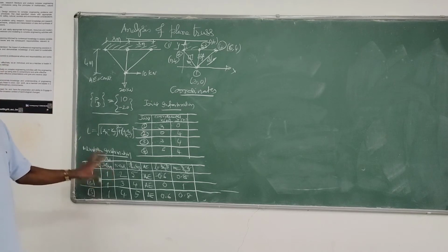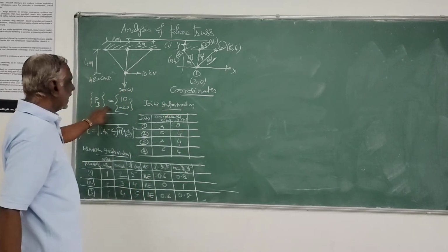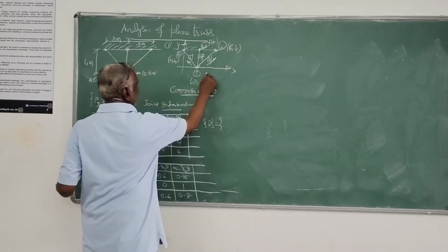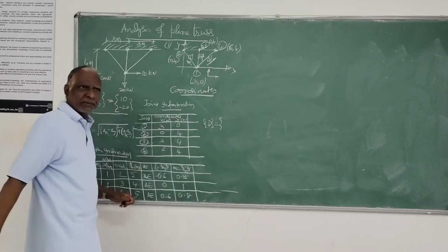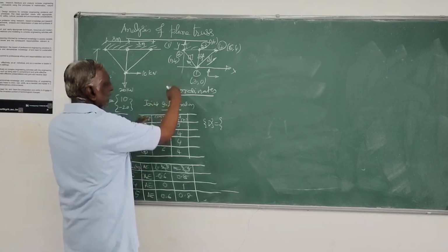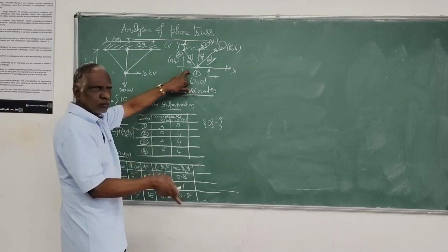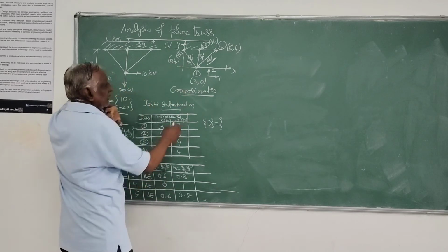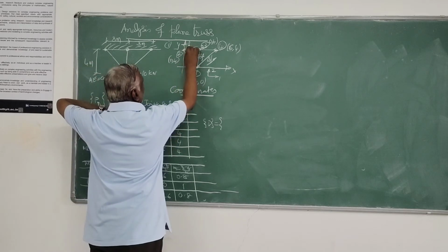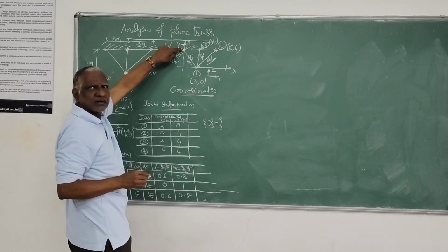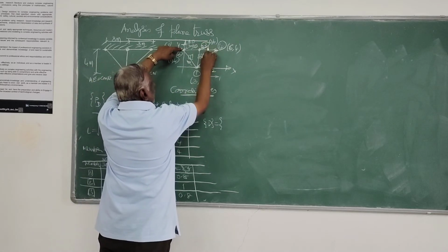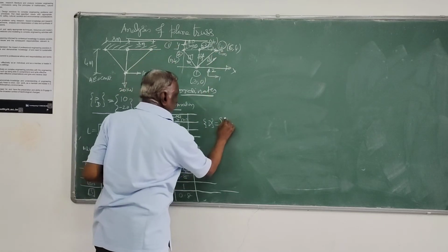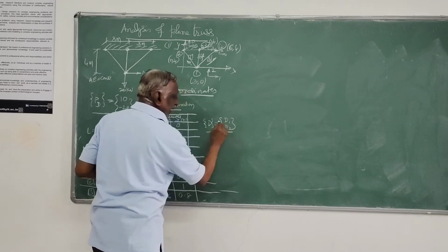That's all the information we need. So now this is the first, PD I have generated, then the PD matrix, then D which we have to determine, or the degrees of freedom I can also write, that is kinematic indeterminacy, as you have done in earlier problems. So here at any joint you can have only 2 types of displacement, no moment. So this is 1 and 2, you can always start with the joint where all displacements are possible, so that you can number first 1 and 2. Here no displacement is possible because it is a fixed support. Here it is 0, 0. Here also 0, 0. Here also 0, 0. Therefore, the unknown joint displacements are D1 and D2.